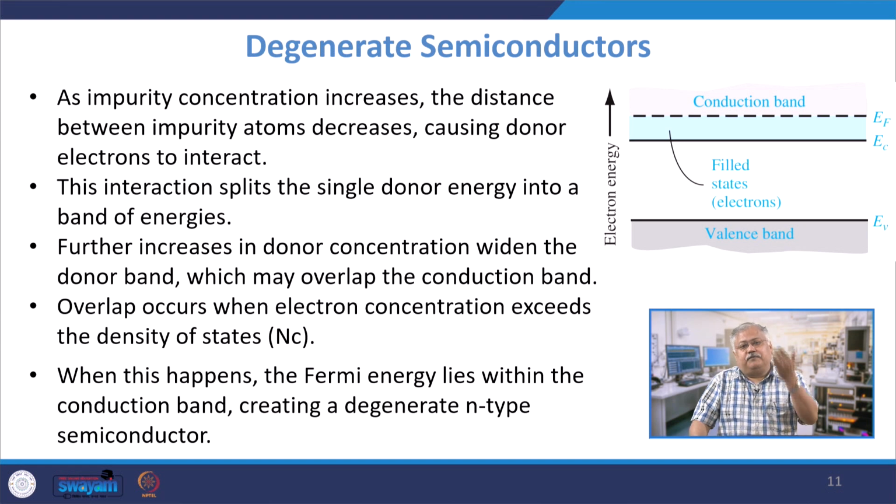Now what if I do a reverse doping, and add p-type dopant species, or acceptor ion dopant species? Then the free electrons will combine with holes. If I would have doped with, let us suppose, an extra 100 electrons, and then I put, let us say, 90 acceptor ions, then you will have 90 holes available. The effective number of electrons now will be 10 rather than 100. This is known as a degenerate semiconductor, right. So, this is the methodology of formation of a degenerate semiconductor.